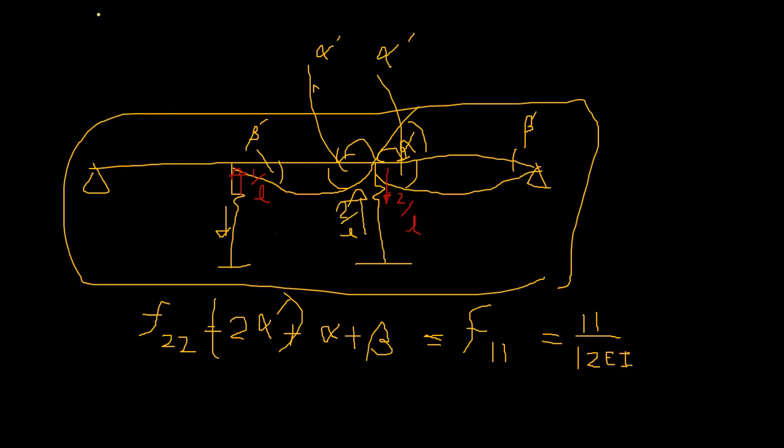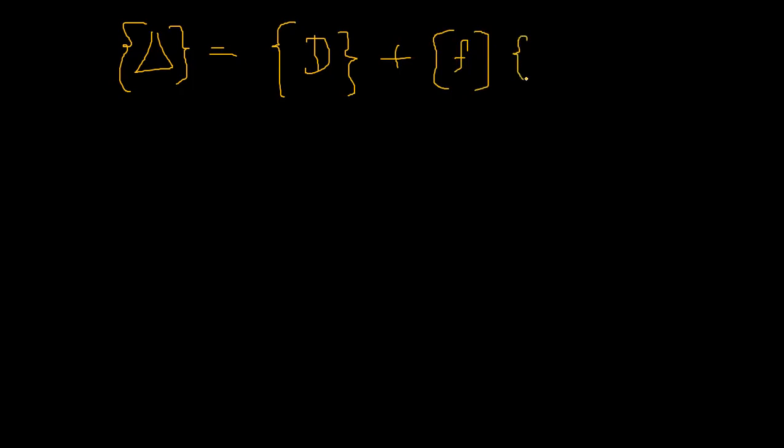Okay, so you can go ahead and write the displacement equation. The displacement in the original structure is equal to the displacement at that joint in the primary structure plus the flexibility coefficients into the force matrix. So your force is now bending moment B and C. Right here you saw at B and C the relative rotation was 0. Why? The beam is continuous. After adding a hinge, you got a displacement, but the displacement was the same, right?